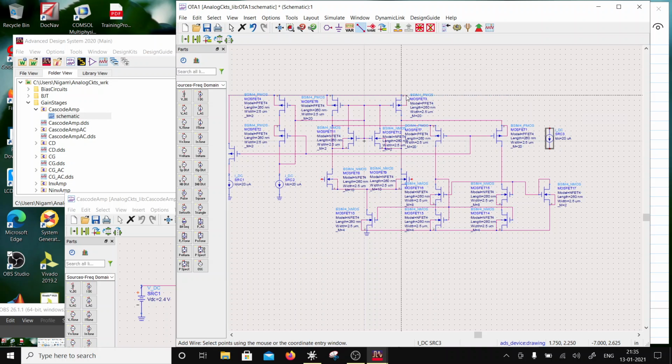So I will drive this with the current here, because this is an NMOS. So PMOS is going to, so this is half the current, so the overdrives are going to balance. Okay, so now we are ready with this op amp. This is the output node, and then I can put some compensation capacitor, right? So the output node would have a compensation capacitor across here, right?